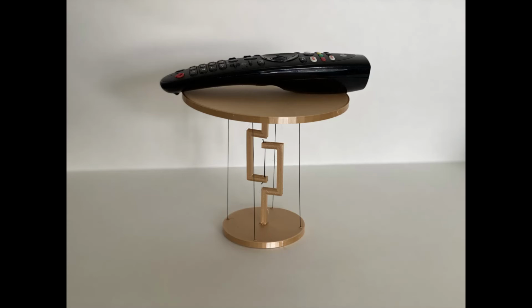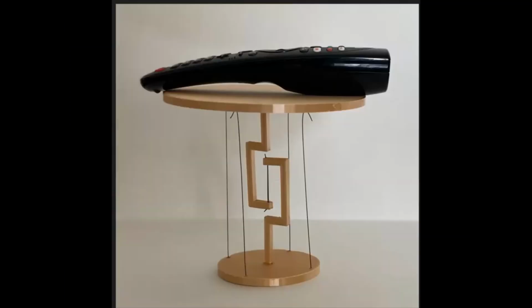Due to the shape of the two solid linkages, the center string holds both platforms in a counterintuitive way. In principle, it makes it so that the bottom platform is actually holding the upper platform in the air through that center string, and the four strings on the outside of the object simply hold the orientation of the top platform into an upright position. If the top platform tries to lean in any direction, the opposite guideline will pull in tension, holding it straight up.